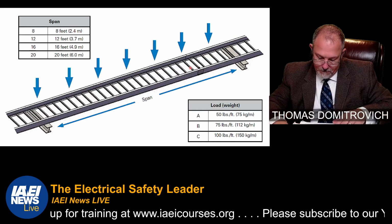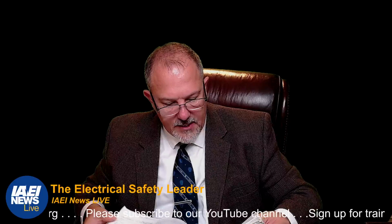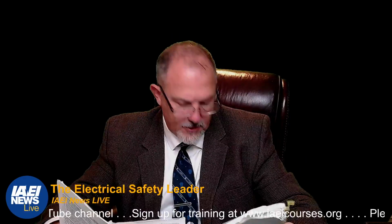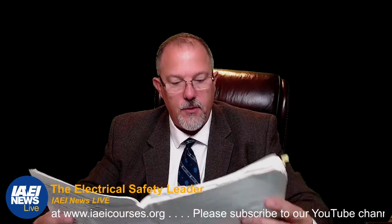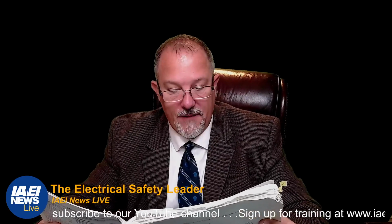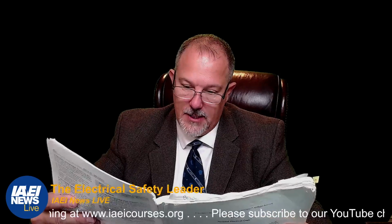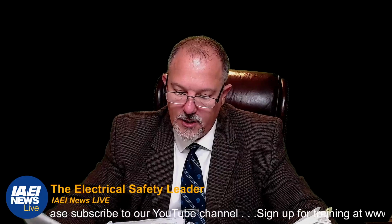Now, let's take a look at what the code says. Cable tray complete system covers in portions or runs where additional protection is required. Covers or enclosures provided for the required protection shall be of a material that is compatible with the cable tray. They have your troughs, your partitions and walls. Discussion: cable tray shall be permitted to extend transversely through partitions and walls, or vertically through platforms and floors. So there's your marking. I'm just looking to see cable and conductor installations. Cables over 1,000 volts and operating 1,000 volts or less. Number of multiconductors, ladder or ventilated trough trays containing any mixture of cables. So this is getting to your different types.